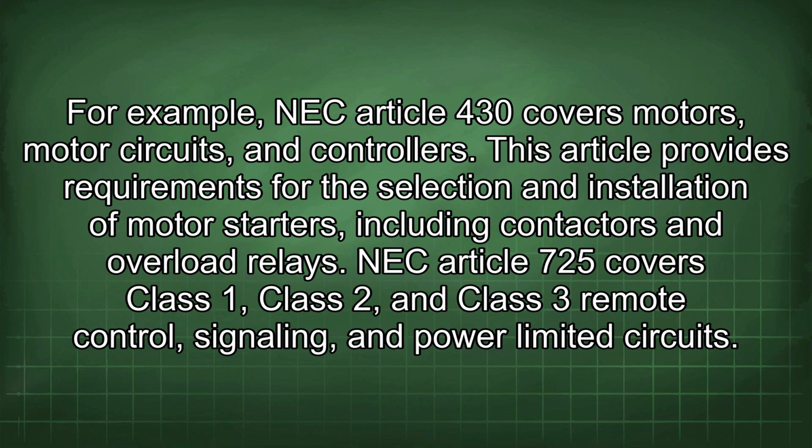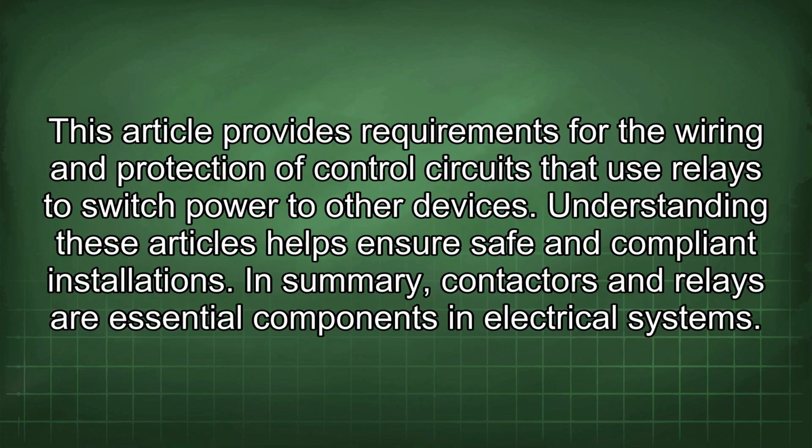NEC Article 725 covers Class 1, Class 2, and Class 3 remote control, signaling, and power-limited circuits. This article provides requirements for the wiring and protection of control circuits that use relays to switch power to other devices. Understanding these articles helps ensure safe and compliant installations.